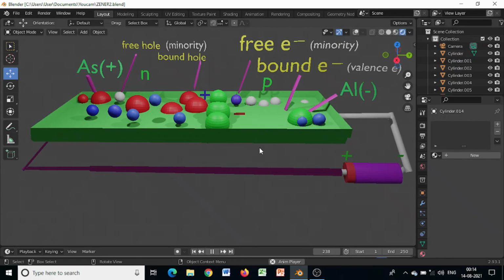As if a large electric field at the junction tears the electron out of the covalent bond, naturally a hole is left in the p side, as if holes are coming from the n side to the p side. Electrons are tunneling through this potential.